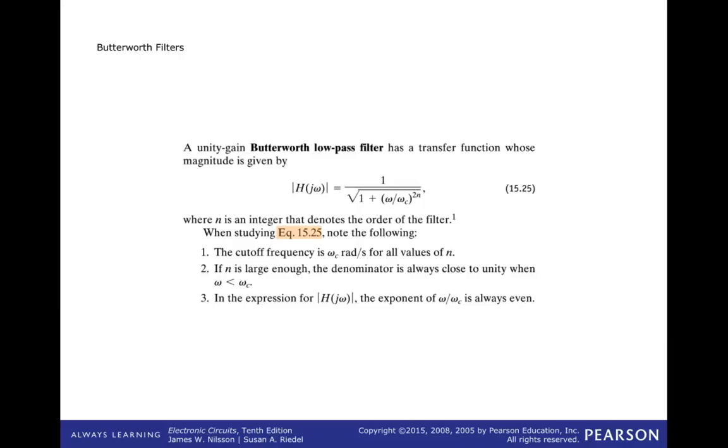Now, we have discussed some of the issues with using cascaded multiple higher order filters. Mostly the fact that the transfer function is multiplied, and as it is multiplied, it shifts the cutoff frequency and narrows the bandwidth, or moves the cutoff frequency of a low pass filter to a lower level.